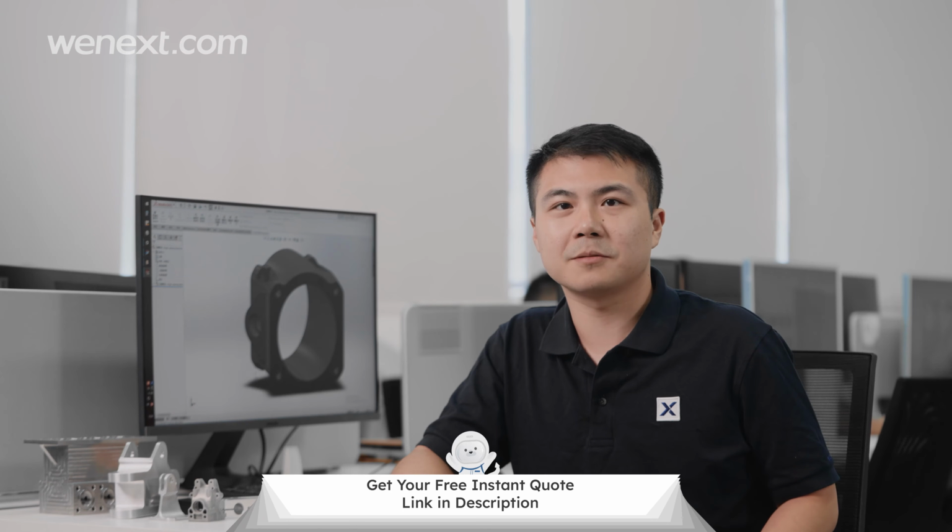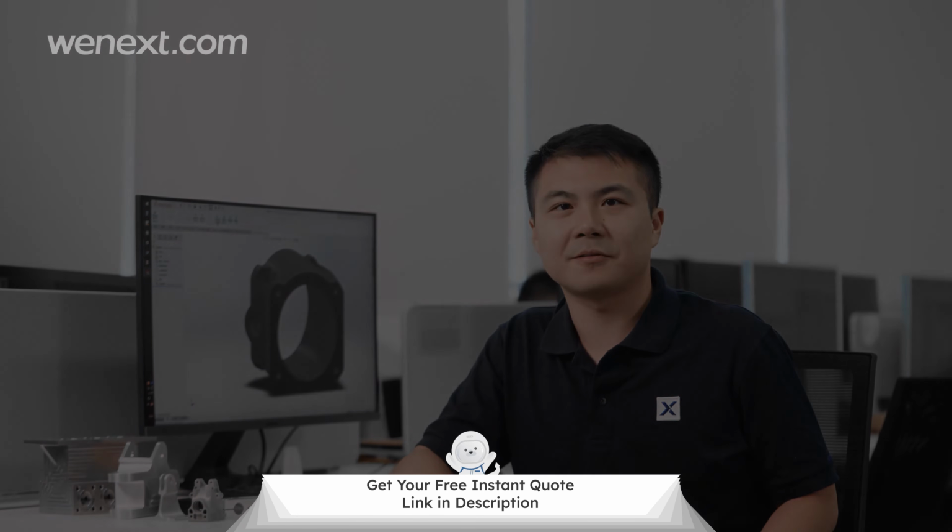If your parts require tighter tolerances and more complex geometries, 5-axis could be a better choice. If you just need a better and faster way to machine parts with simpler structures, then 3+2 is more accessible. Both full 5-axis and 3+2 have unique advantages. Choosing the right technique benefits your manufacturing process to increase your profits. There's no one-fits-all manufacturing technique.